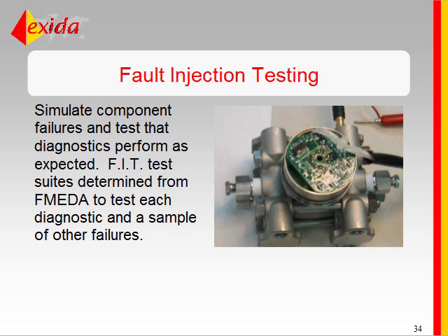For 61508 certification, if you claim diagnostic coverage factors above 90%, you're required to verify those numbers with fault injection testing. In other words, if you have a good diagnostic coverage factor, it's not enough to do an FMEDA. The FMEDA must be verified with good fault injection testing. And of course, the FMEDA can be used to document fault injection test results.